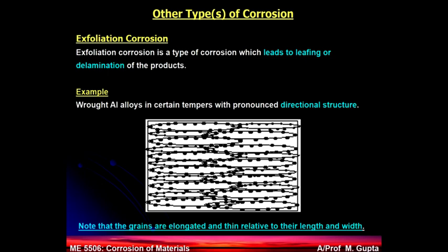Now, if you are dealing with high strength alloys, the high strength comes from the second phase. So when you have a directional structure and you have a high strength alloy, then this second phase, you can see as dots here, the black dots, they tend to precipitate at the grain boundaries. But the grain boundaries are the defect zones, so they want to precipitate there.